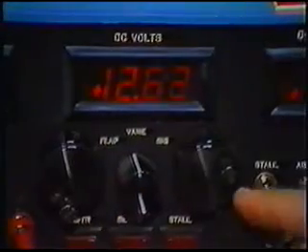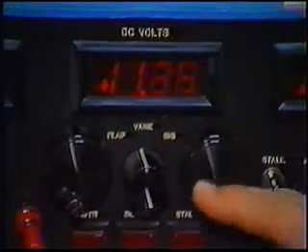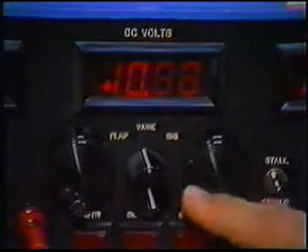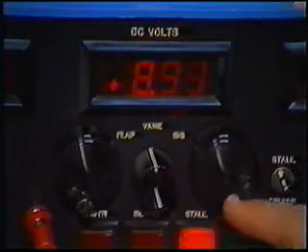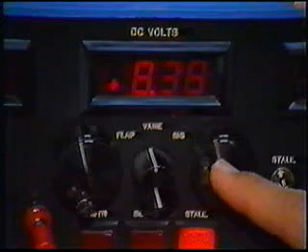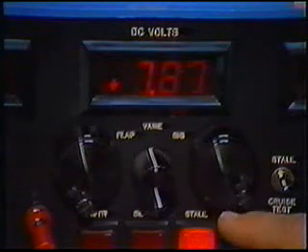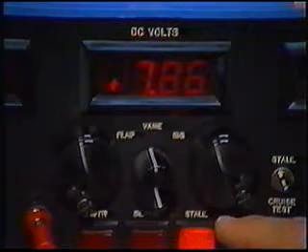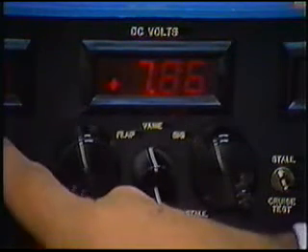Depending upon the maintenance activities involved, it is usually a good idea to check the vane and flap position transmitters as well. The SAS tester allows this to be easily accomplished. The vane must be locked in place on the fuselage using the location tool. Check to see that the proper voltage is present using the tester.